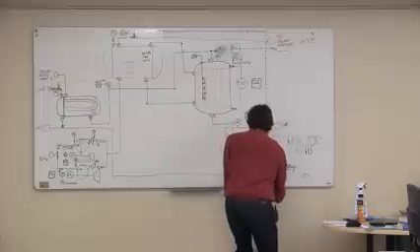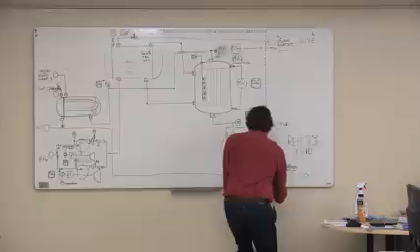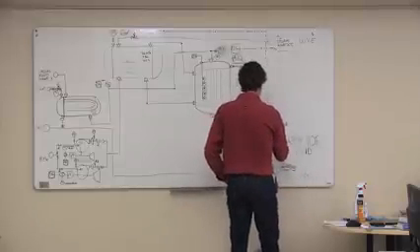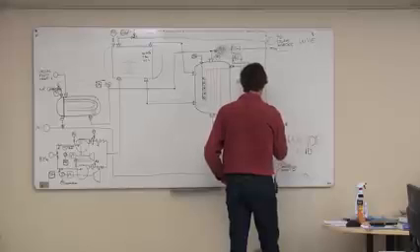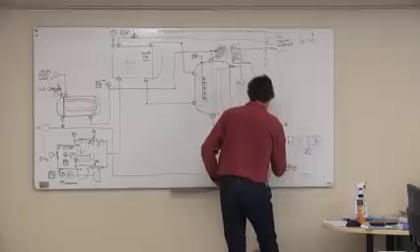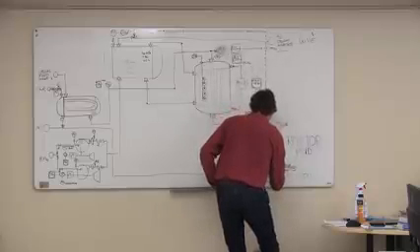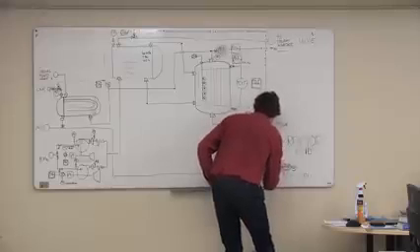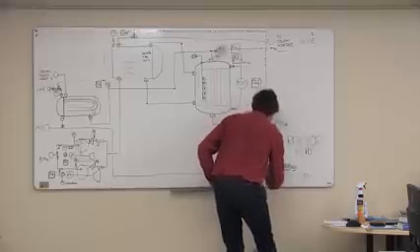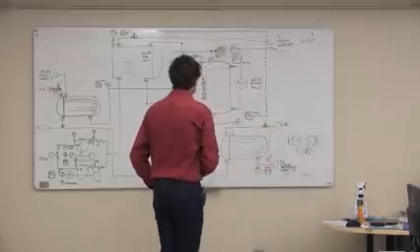And we need a temperature indicating controller in order to do that, like that. We need some cooling water controls. It's cooling water, so let's fail it open. Actually, what we can do is come down here. There. Okay, so that's our cooling water.